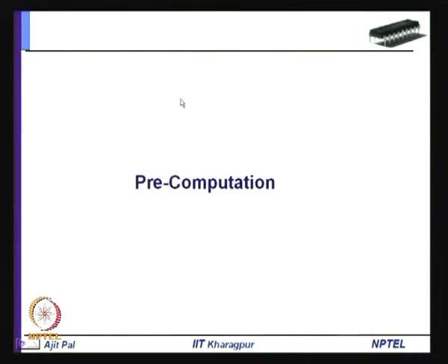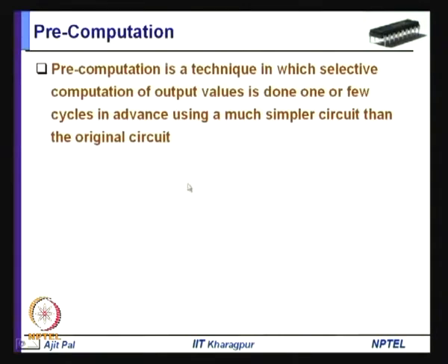Now, we shall consider another very interesting technique, that is called pre-computation. Pre-computation is a technique where selective computation of the output values is done one or a few cycles in advance using a much simpler circuit than the original circuit. Your original circuit may be performing a very complex operation, say multiplication of n bits, addition of n bits, or something more complex.